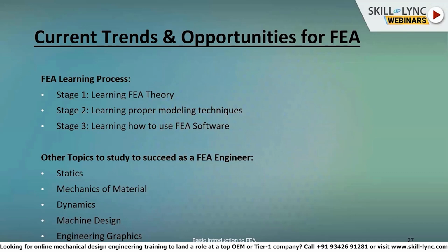So it is good to go with basic theoretical knowledge about FEA. Then second, you have to be good with modeling practice. Based on the shape of the geometry, you should be able to decide what type of elements you are going to use and what type of behavior you want to capture.